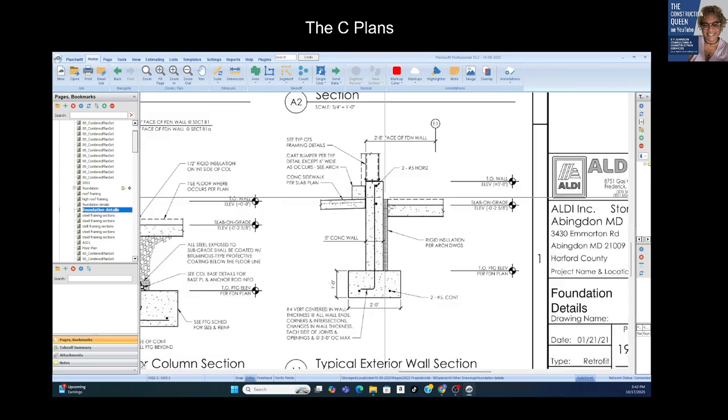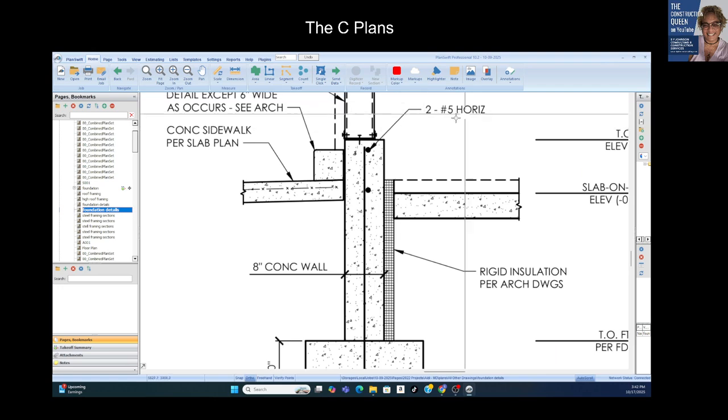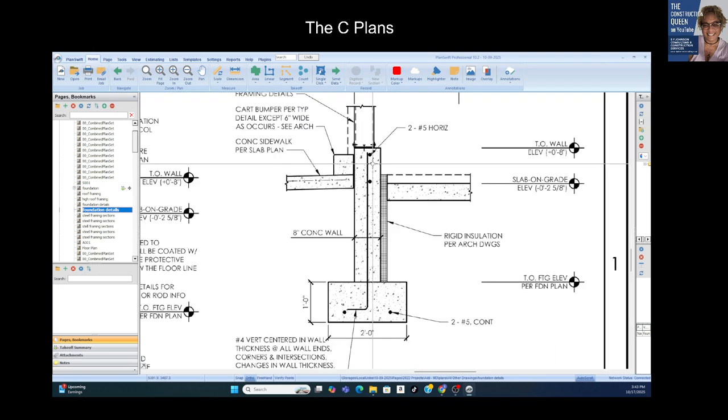Okay, and then you work your way, you just go all the way up. And then we have two number 5s horizontal along the perimeter. So basically, in terms of rebar count, it doesn't make a difference, it's the same. So you have four number 5s on that perimeter, and then however many of those L's you have. And now cubic yards: you turn everything into cubic feet first and divide by 27. That gives you how many cubic yards of concrete.